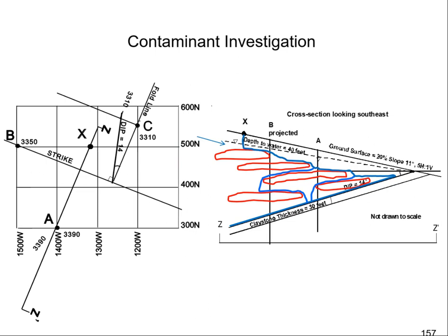The question number 58, why is A the best answer? Because the borehole penetrates the clay layer. Well, out of the choices that we have, borehole B is not a viable answer because it's uphill of the site. And there isn't any reason to believe that the contaminants wouldn't reach the confined aquifer. We don't have enough information to determine that they wouldn't.